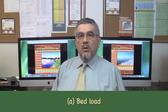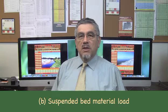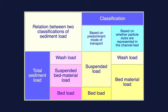As sediment enters a stream or river, it separates into bed material load and wash load. In turn, the bed material load is transported as either A, bed load, or B, suspended bed material load. The sum of suspended bed material load and wash load constitutes the suspended load of the stream or river.